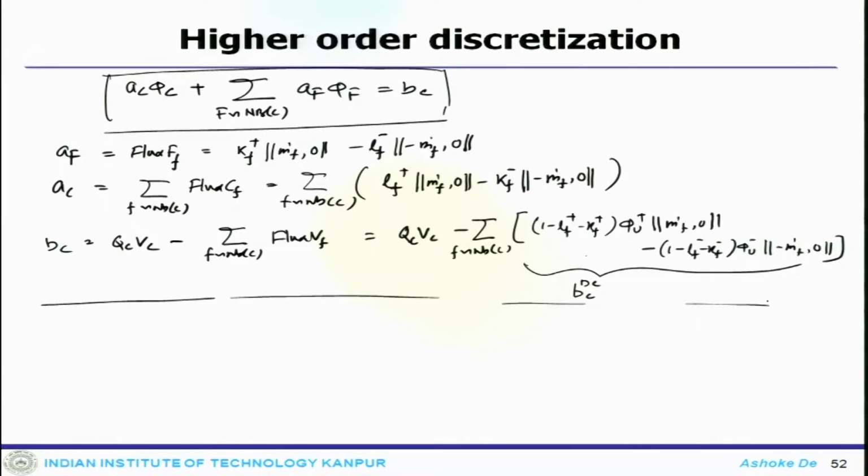The full implicitness of the method on an unstructured grid, with phi u being an actual node in the computational domain, can be resolved in the algebraic equation. So, that has now a larger stencil that includes the far nodes EE and WW.